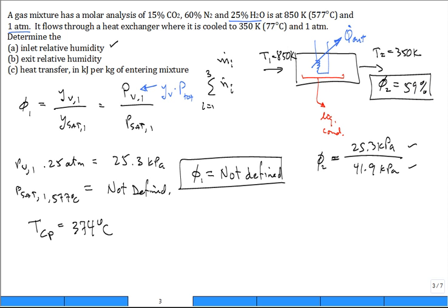So if you continue to cool it, it'll probably get to the dew point temperature, and at the dew point temperature, relative humidity will be 100%, and if you cool it anymore, you're going to have the liquid coming out of that drain pan. True? But at this point, there's no threat of condensate draining off of that cooling coil.